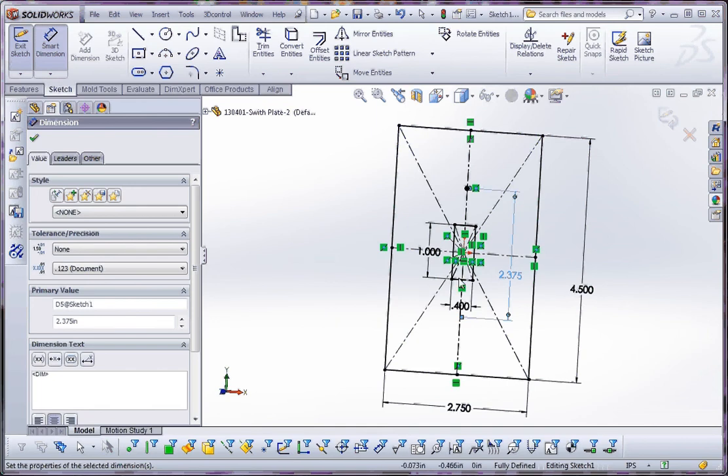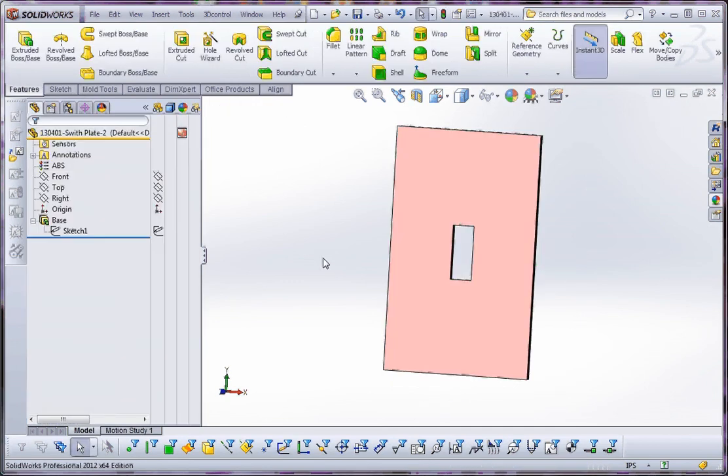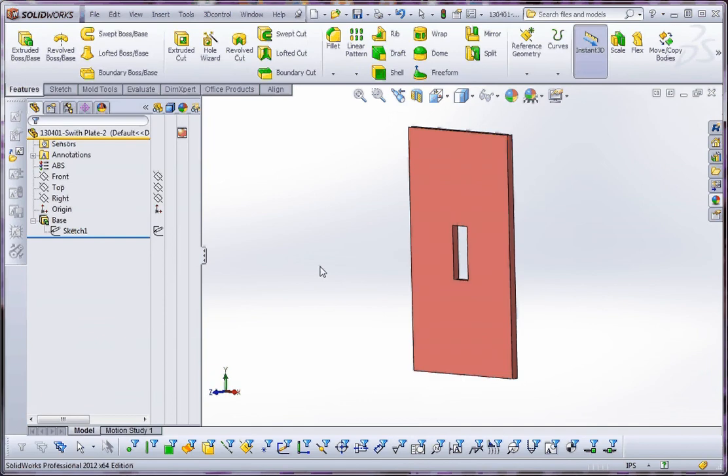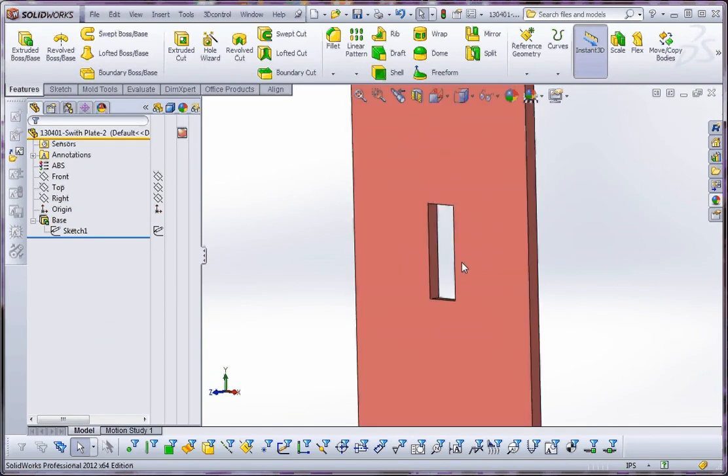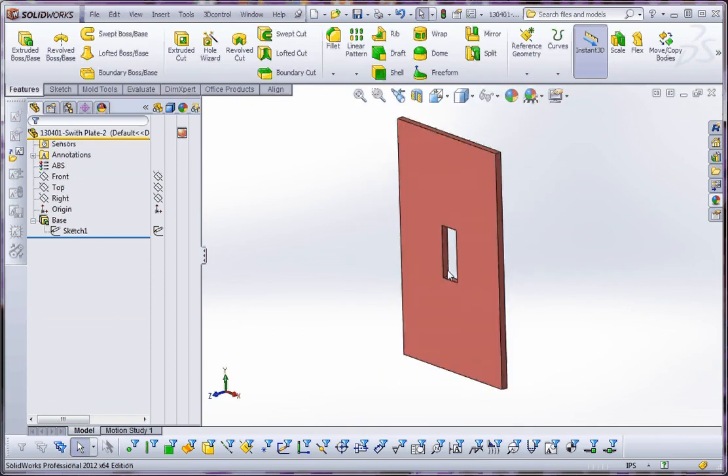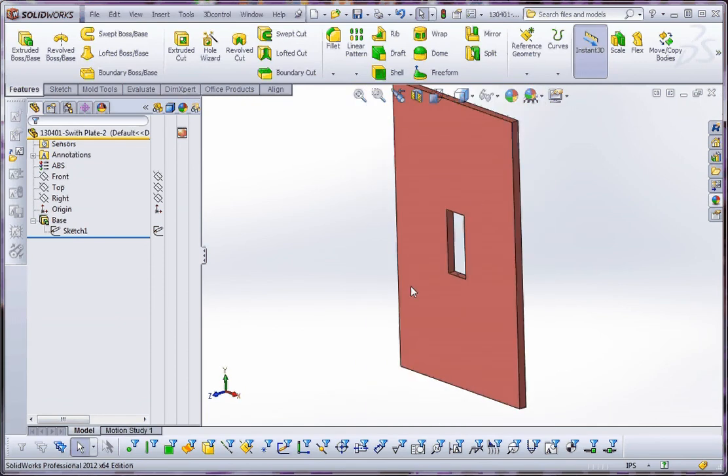And when it gets to this line over here, it's going to put a void on the inside, which may not be exactly what we want. But let's go to the rebuild, and maybe we do want to do that. The drawback of having one feature that defines not only substance and a hole is if you want to do something with that hole, like create a linear pattern, you have to define this whole thing.